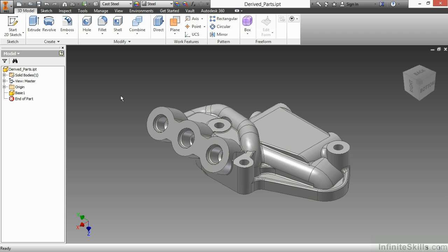So in an example, let's say I have a standard casting from which we create all these different machinings, let's say 20 or 30 different machinings based on one standard casting. What I would like to do is have one casting file that is then a master file, so that when changes are made to the master, the children machining operations, the children machining files, would also then update. And I do have them as separate trackable files because each one of those machinings had to be separately trackable for purposes of part numbers, or let's say a customer needs to reorder another one. I need to have them as separate entities.